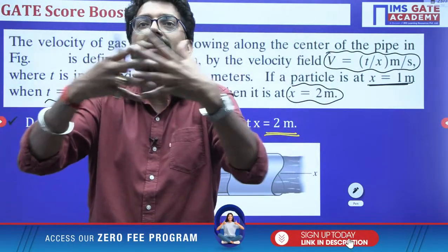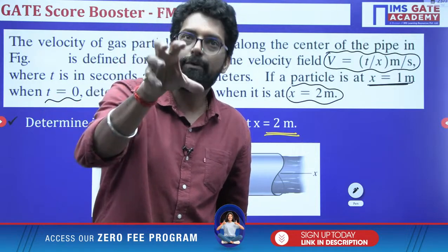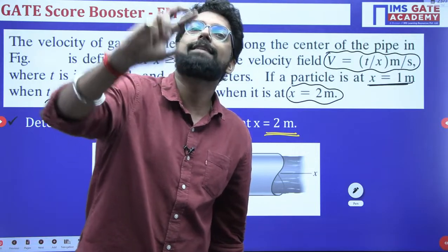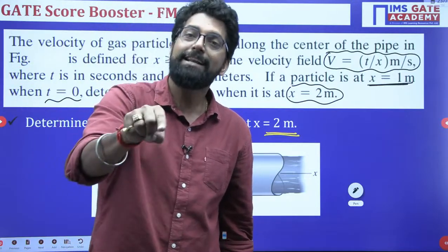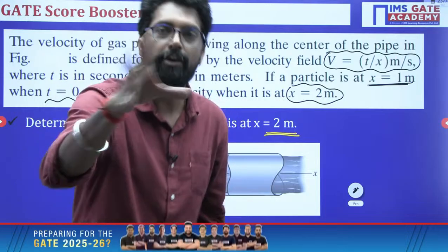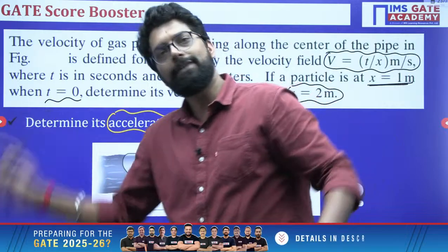The Lagrangian and Eulerian approaches merge when the tracked particle has the same property as that of the field property. In that sense, essentially the Lagrangian approach will merge into the Eulerian approach. Otherwise, both are different. One is the particle analysis, the other is the field analysis.